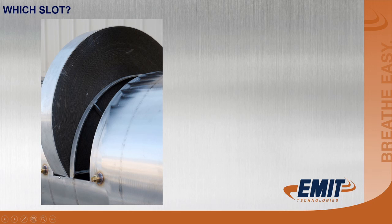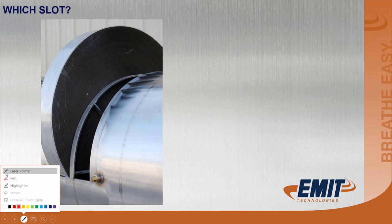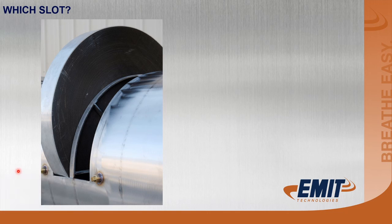The slots in a catalyst in an EA housing make no difference which slot you put your element in. If you're only going to put one element in, some of the things that we think about are, if the catalyst does have a catastrophic failure, we usually like to put it in the front slot right here. The reason being, when you have a catastrophic failure or an over temperature on a catalyst, it's hard to get that catalyst element out, and you'll want to be able to get to the back side of it and get your pry bar in there and start removing the catalyst element.